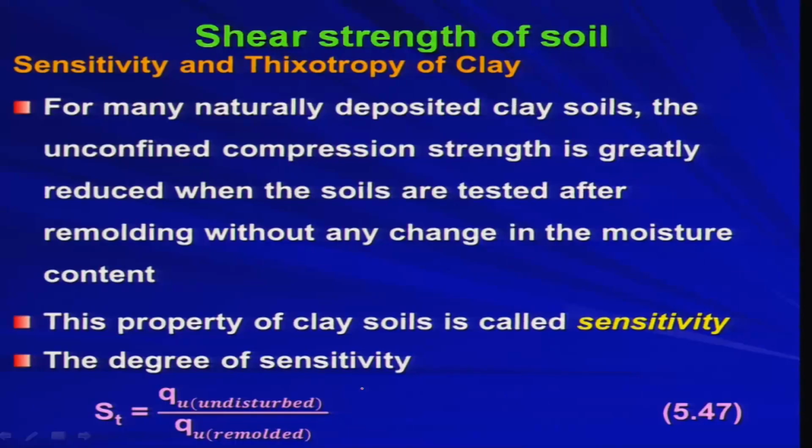Whatever soil is lying in the in situ condition in the field, that is your undisturbed soil. Now, you are collecting the sample for doing the laboratory test to find out the shear strength. How will that shear strength be affected, or what variation will you get in the shear strength parameters, between what you expect from the field, that is the undisturbed sample, and what you get from the disturbed, remolded sample? That is known as a remolded sample. That means you are remolding the soil to perform the shear test.